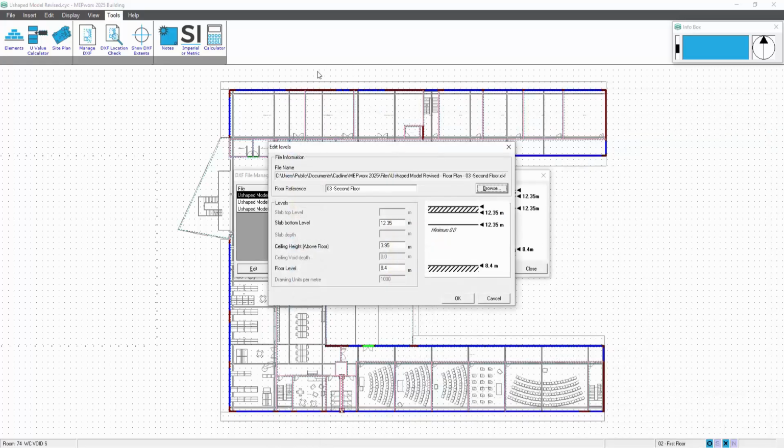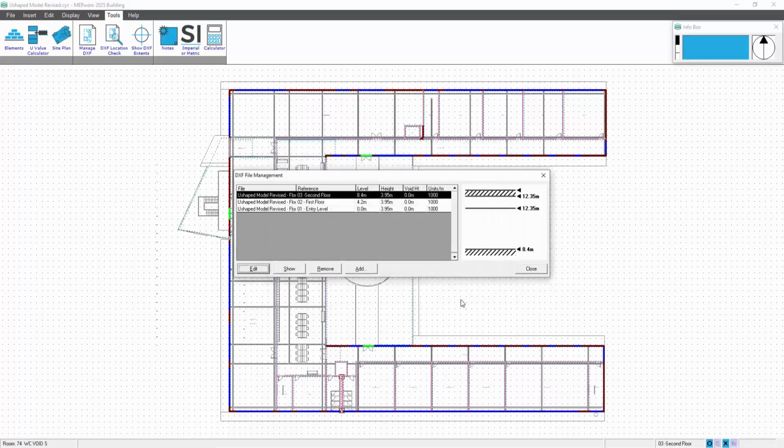So it's important that the original DWG from the source 3D architectural model is used as the backdrop. The dynamic simulation software would have been traced over the top of that to generate the room spaces, so they will correspond. So you're effectively taking the GBXML from either IES or TAS, the results from IES or TAS, and then superimposing the detailed DXF file underneath them.